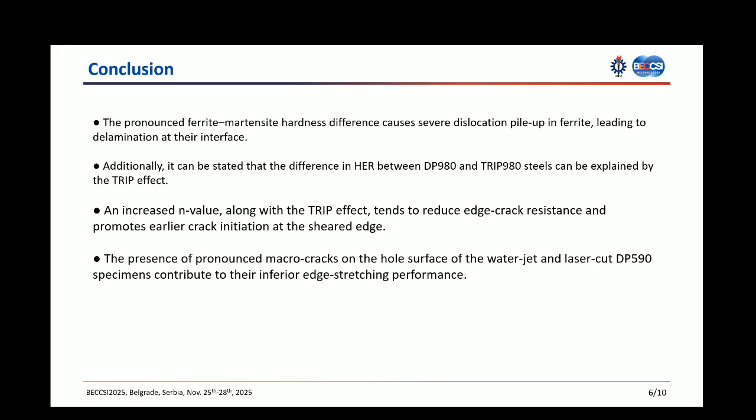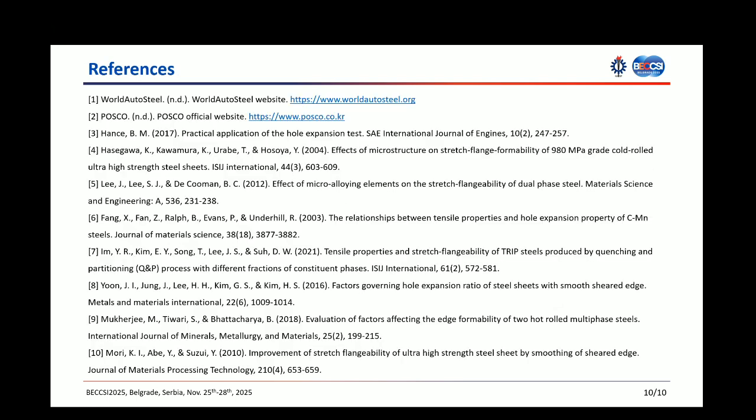The presence of pronounced microcracks on the hole surface of water jet and laser cut DP 590 specimens contributes to their inferior edge stretching. And this is a valuable conclusion that you can use for designing a stage when you work with the AHSS family. And this is the reference page.